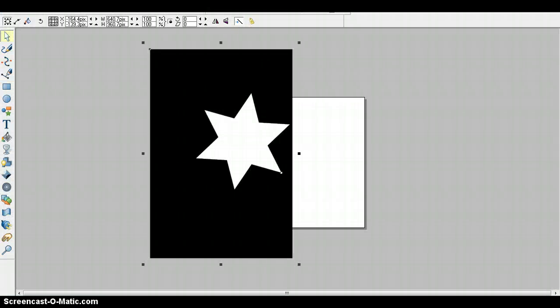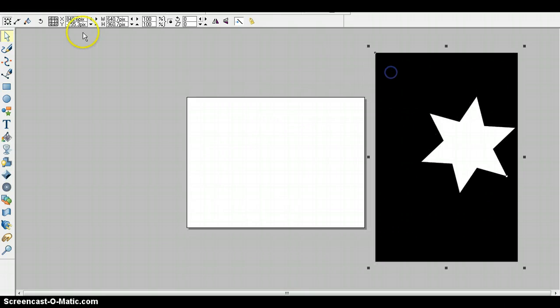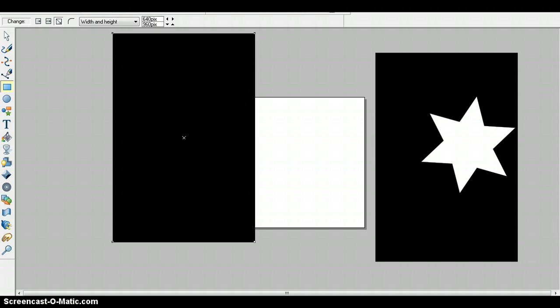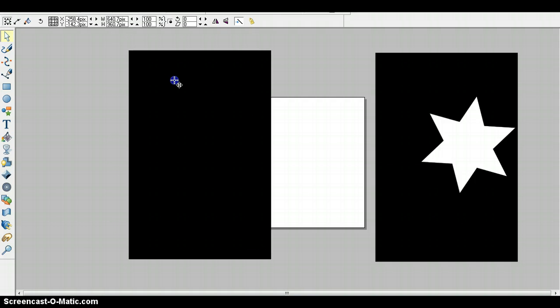So what I do is I go into Xara, and here's one I made earlier, but I'm going to show you how I did that. So I'll move that away. I choose the rectangle button and I make a basic rectangle, but this isn't the size, and I can see that because the size is wrong here. I've got to change the width to 640. You'll see it says PIX, pixels, and 960 pixels high. I must press return, the enter button, and I now have the right size.